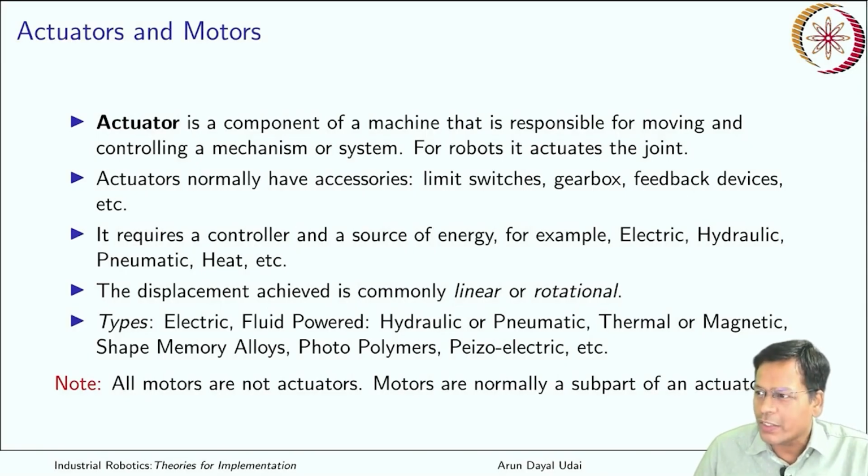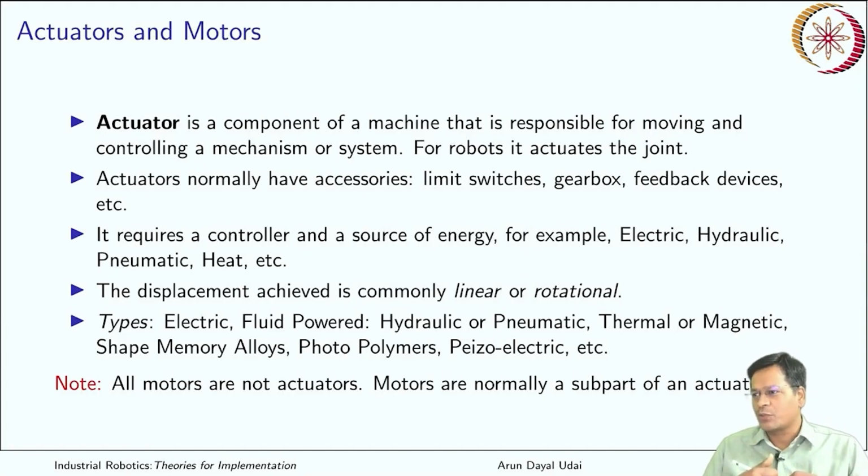So with all these kinds of actuators, not all motors are actuators. Motors are normally a sub part of an actuator, residing inside the actuator, right? So a motor along with its accessories like limit switches, gearbox, feedback devices and all is called an actuator. So now you know the difference here.